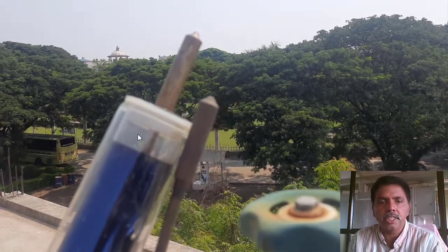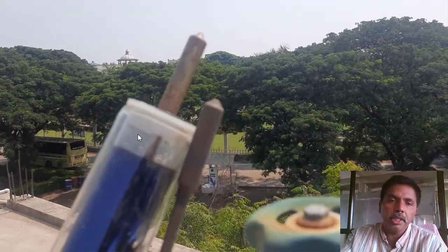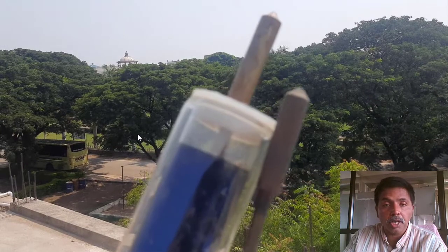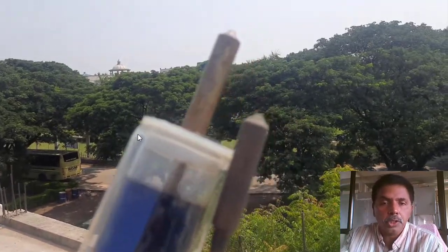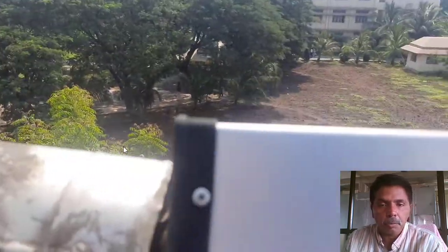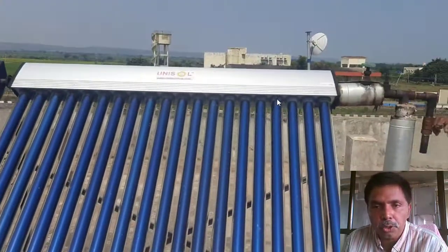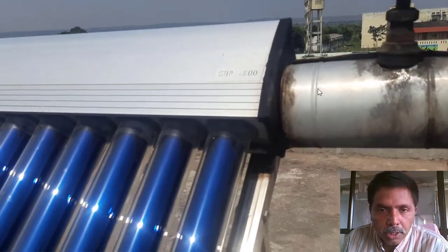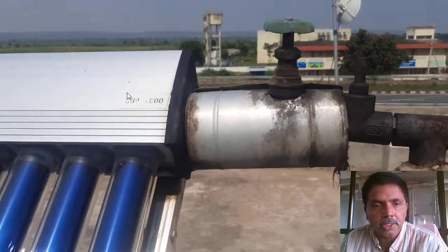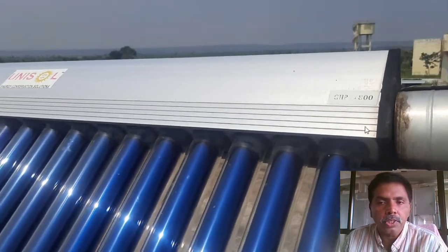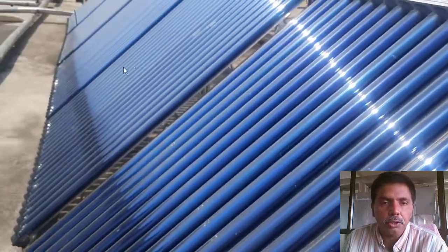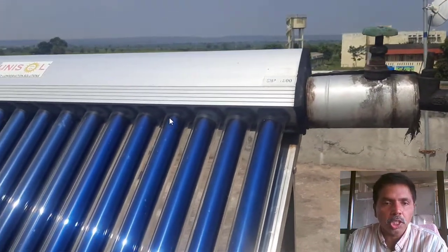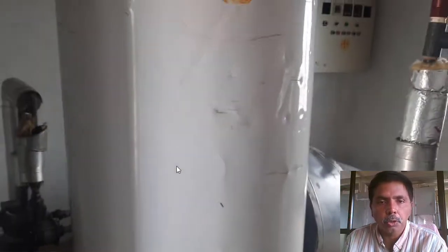Generally, a solar water heater can generate maybe 100 or 200 liters of heated water in a day. But for industrial application with mass flow rate, a 10 degree or 20 degree delta T is required. For that purpose only, this heat pipe based system was introduced. The heat pipe is immersed in a manifold, and the heat transfer fluid flows over the heat pipe condenser unit. Even if some ETC tubes fail, our system does not stop. Generally in a solar water heater, if one ETC tube fails, the total system stops.